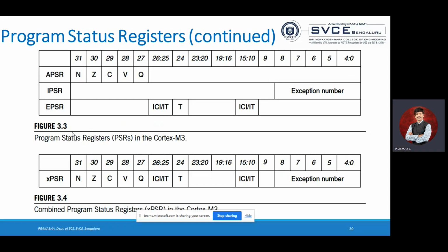So it is not only R1, R2, R3, R4 that you have to check. You should also check the CPSR, to see whether a carry has been generated and at which point the carry has been generated. When you multiply the second bit with the second bit, there may be a carry. When you multiply the fourth bit with the fourth bit, there may be a carry. When you multiply the last bit with the last bit, there may be a carry.